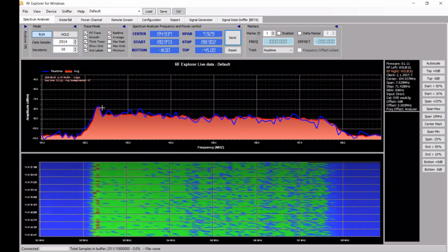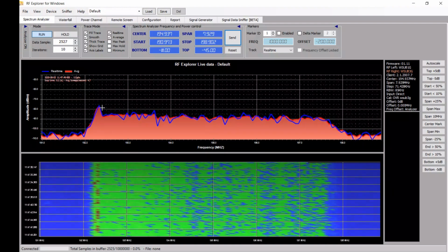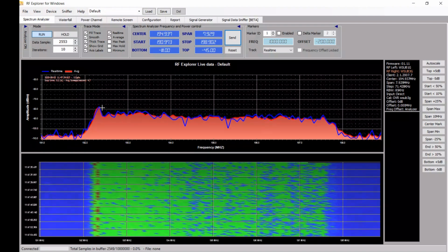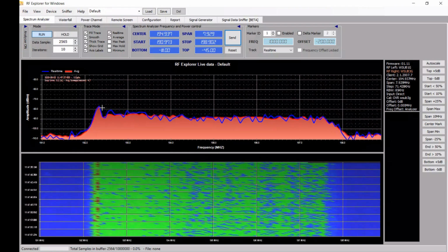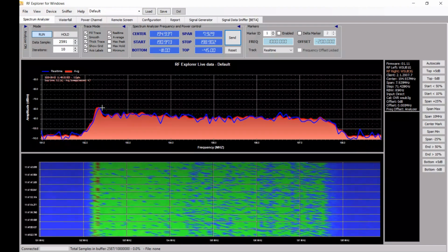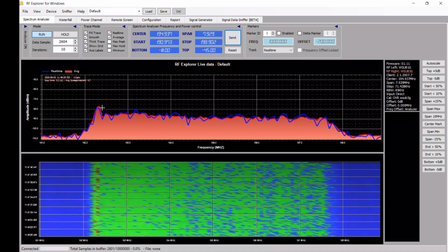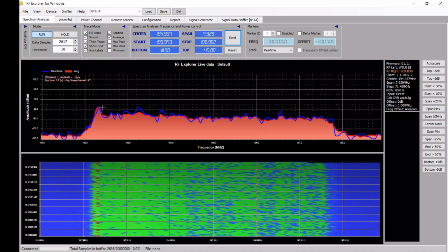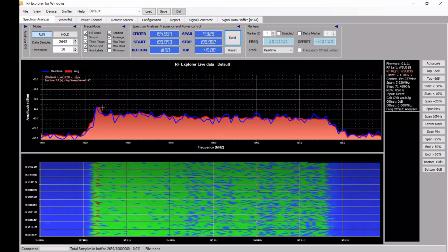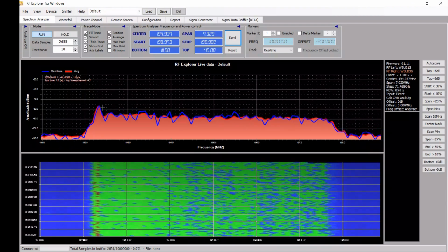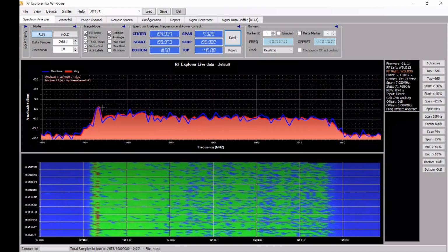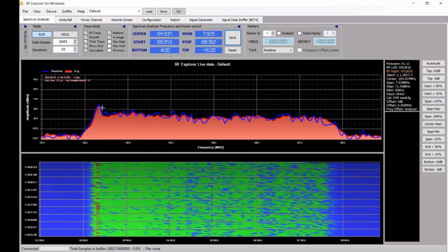Okay, so why do these signal amplifiers work? One, marketing. People think amplifier good, therefore better. The second reason is they do exist for a reason, all right? What can happen is, if you have a very long stretch of coaxial cable, which is not perfect, it will attenuate the signal, and the amount of attenuation is determined by the length of the coaxial cable and its composition. I'm using RG6 coaxial cable here, which is actually quite good. It's relatively cheap these days, and it's quite good.